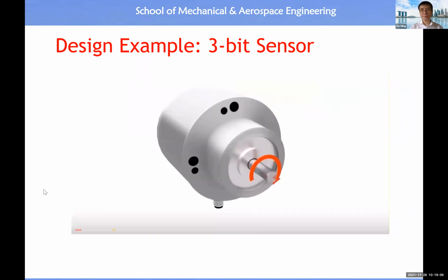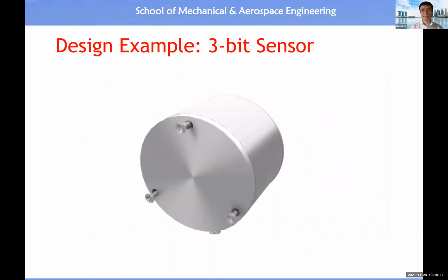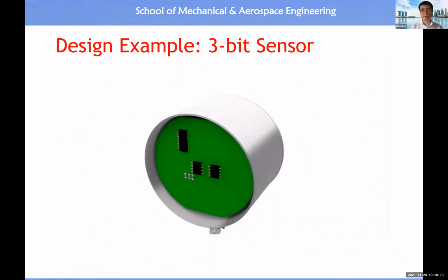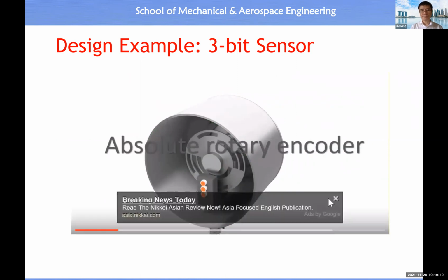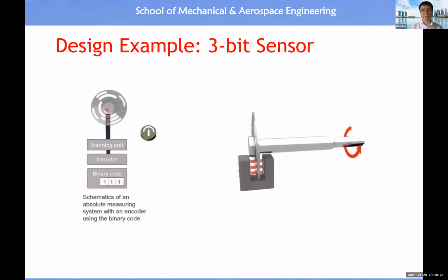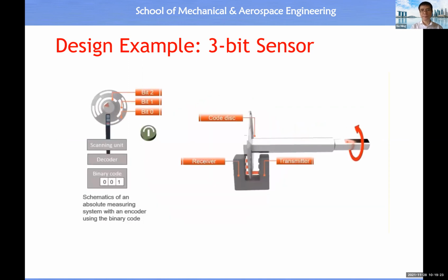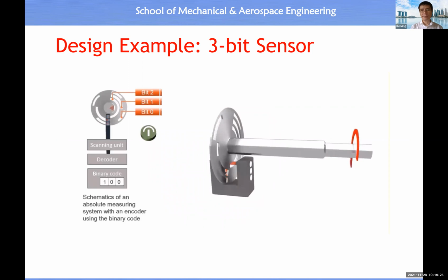You get the function of an absolute rotary encoder, as well as the principle of a multi-turn encoder. Rotary encoders are also named shaft encoders. Measuring systems which use this type of encoder can be classified as indirect and digital.